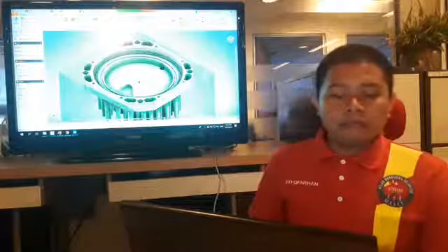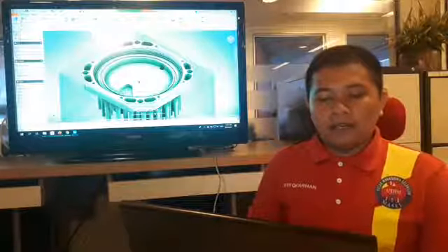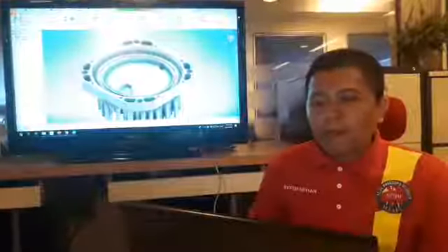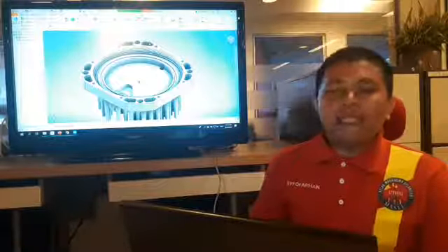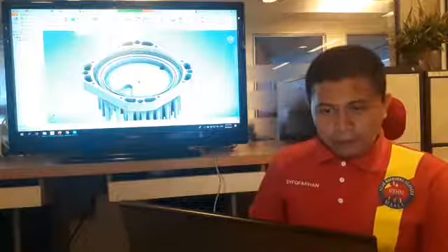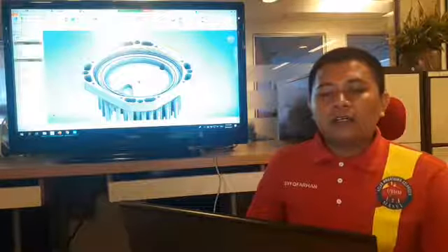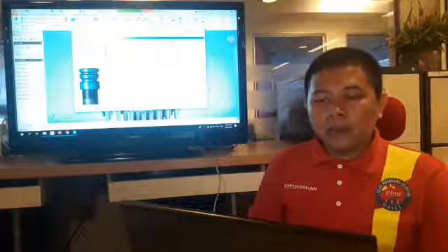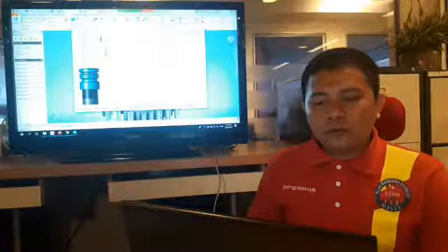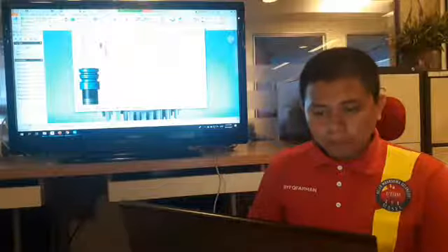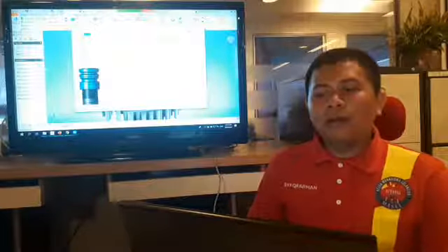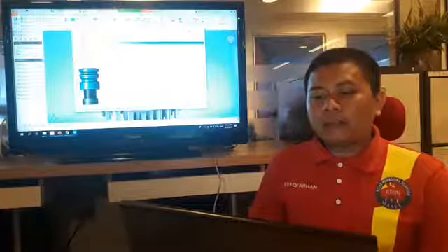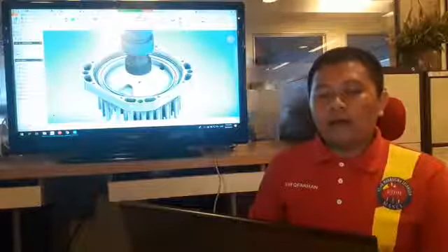Alright, so I go to the next job, next step. Okay, now I want to focus on this area, or maybe the top first. So I want to do the face milling. So I just go here and click on face. Okay, choose the proper tools. For example, for this case, I will just go to the buy type. I want to choose the face mill, and now I just simply choose the 50 mm face mill. Just simply double click, so then it will help us to choose.